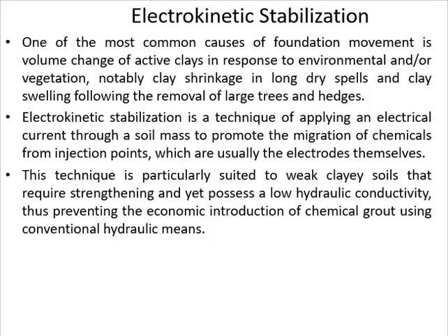This technique is particularly suited to weak clay soils that require strengthening and yet possess a low hydraulic conductivity, thus preventing the economic introduction of chemical grout using conventional hydraulic means.